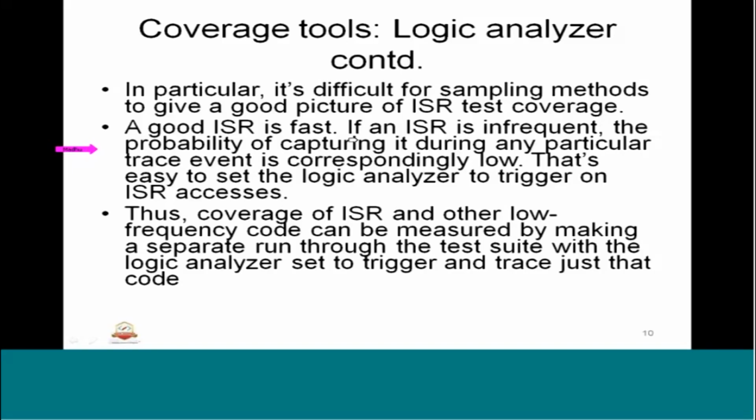If an ISR is infrequent, that means the frequency of the ISR happening in the embedded life cycle is low. The probability of capturing it during any particular trace event is correspondingly low, so capturing the trace data is harder because the ISR happens so infrequently. It is easy to set the logic analyzer to trigger on ISR access, because the capturing mechanism will be easier. Thus, coverage of the ISR and other low-frequency code can be measured by making a separate run through the test suite with the logic analyzer set to trigger and trace just that code.